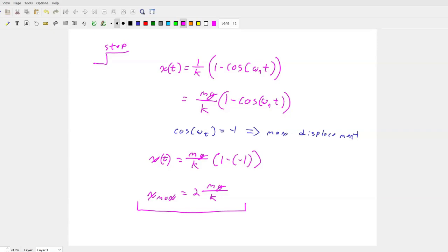It's a good rule of thumb, right? Can you model a dump truck as a 1 degree of freedom system? As someone who teaches vibrations, I would say you can model anything as a 1 degree of freedom system. Is it a useful model, right? All models are wrong, some models are useful. But in a 1 degree of freedom system, your dynamic response to a system is always twice your static response. In an engineering sense, it's a very good rule of thumb.